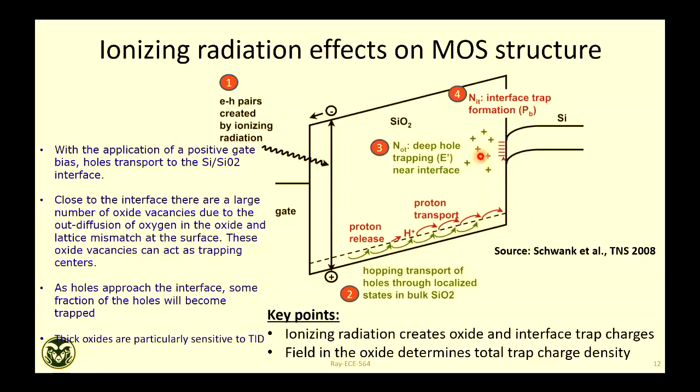Typically silicon dioxide has a lot of imperfections inside, closer to the interface, because of the bonds at the silicon interface. There can be some oxygen vacancies because of processing-related issues. Those oxygen vacancies will trap those holes. So this is your hole trapping process. Number one, electron-hole pair generation. Number two, hole transport inside the oxide. Number three is hole capture, or hole trapping, inside the oxide material.